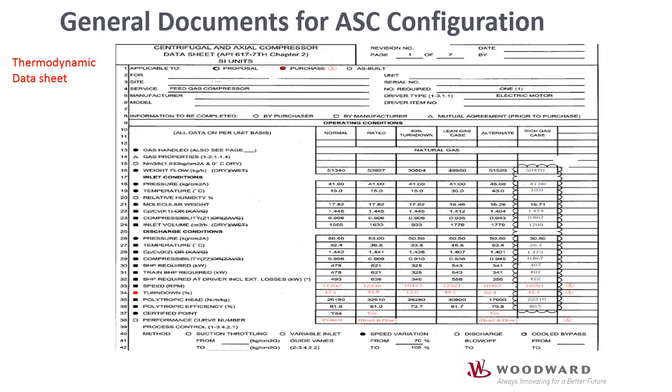If no specific information is given by the customer for specific operating conditions, we select the most used or most common operating condition for the configuration. If we feel that all operating conditions are equally used, then we select the most conservative condition, preferably the one where you get the highest flow at rated condition. That's the operating case we will select.